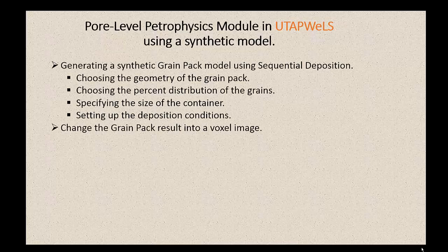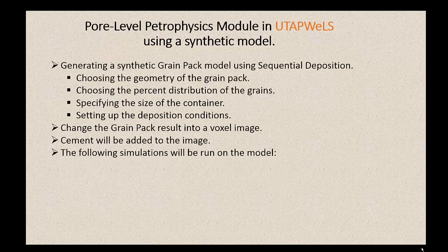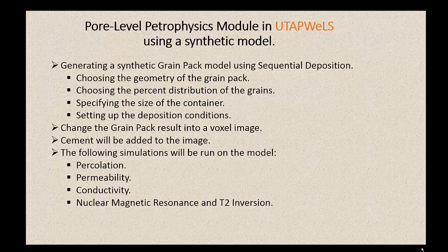The grain pack result will be converted into a voxel image. Cement will be added to the image. The following simulations will be run on the model: percolation, permeability, conductivity, and nuclear magnetic resonance and T2 inversion.